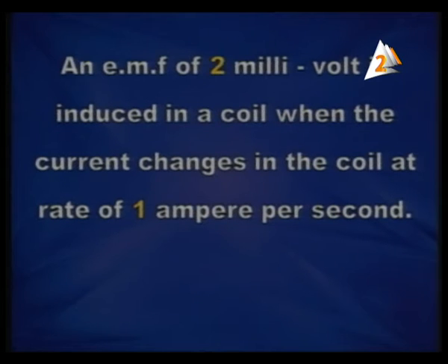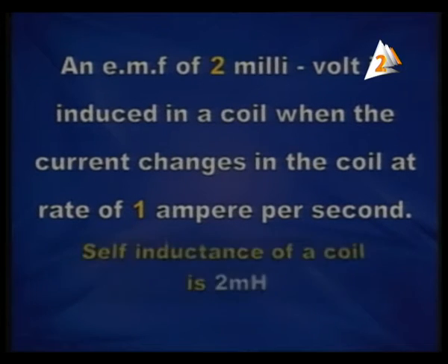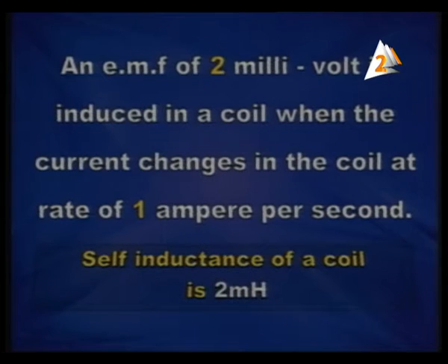An EMF of 2 millivolt is induced in a coil when the current flowing through this coil changes at a rate of 1 ampere per second. What does this mean? Yes, self-inductance of the coil is 2 millihenry.